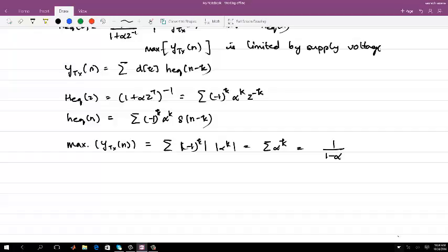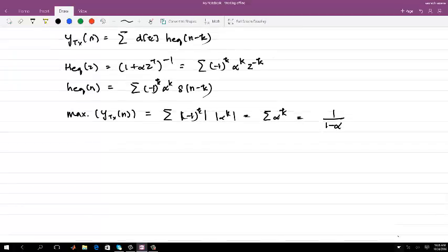No, alpha is a channel thing. So if my alpha increases, I have to change the alpha here. But at the other point I am limited, so I have to normalize something, right? Normalize the output transmit amplitude. Okay, so this is what you have seen as an ideal equalization. If I want to normalize, there is a certain limit, like my supply voltage.